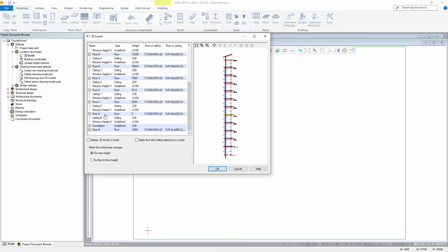The floor type height levels have been set up as main levels and can be changed freely. Ceiling type height levels are sublevels and are located some distance away from the associated main level. The distance is equal to the total thickness of the selected floor system. If the main level changes, the subfloor level will change with it, whilst maintaining that distance.